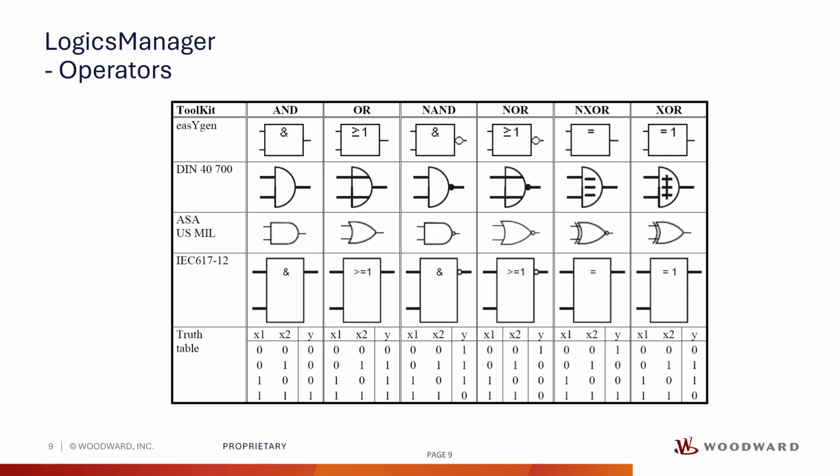Here is an overview of all the 6 available logical operators in the LogicsManager, the different symbols, and for quick reference you can see the truth tables for each operator.